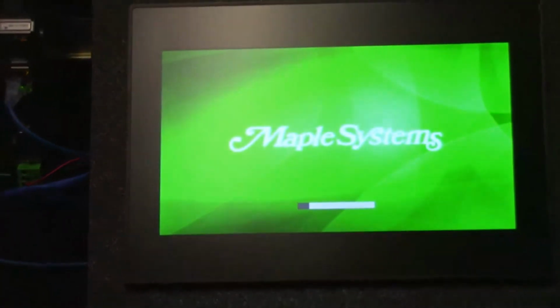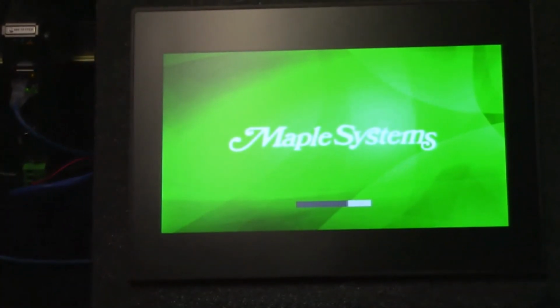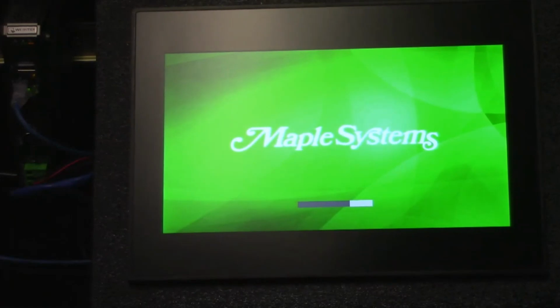Specifically, what we're connected to here is a headless HMI, CMT FHDX 820, which does also come with an HDMI display, but also has the feature to broadcast the project over the web via Easy Web. And then within Easy Web, the specific application that we are going to use is called WebView. That's what we're actually going to use to broadcast the project over the web.